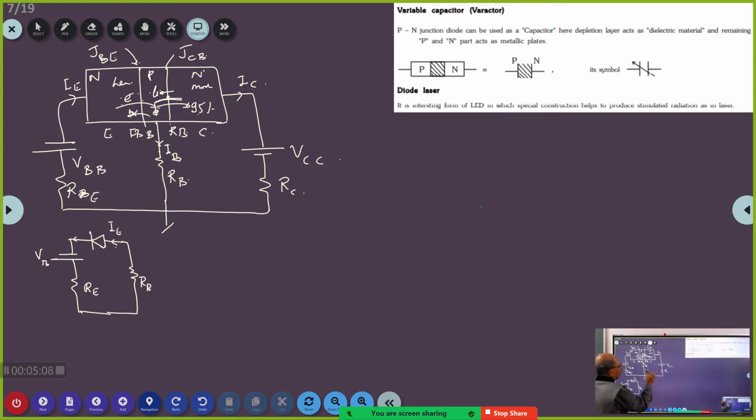So this current is reverse bias. So everybody say yes, sir. So you know the reverse bias characteristic will be like this. That means over a large variation of this voltage, the current is constant. So therefore, this electron current, I will show it as a current source, not as a voltage source. Agreed? Reversed. As a voltage source. Agreed?